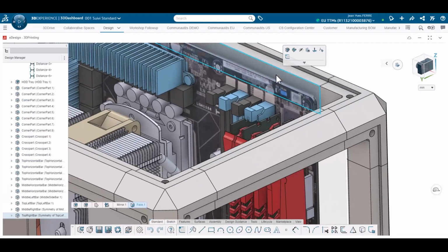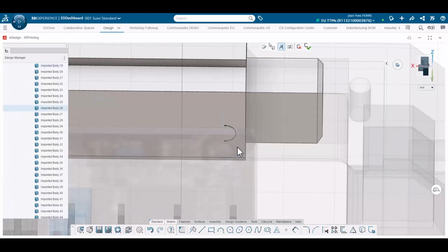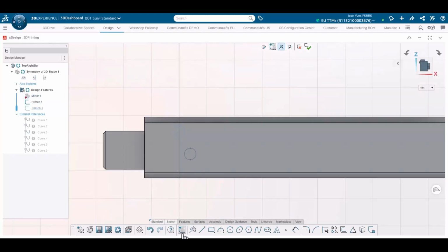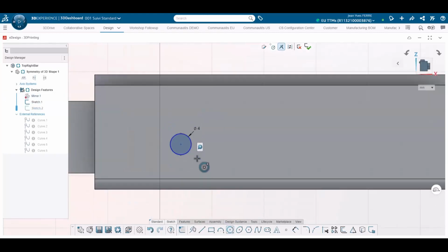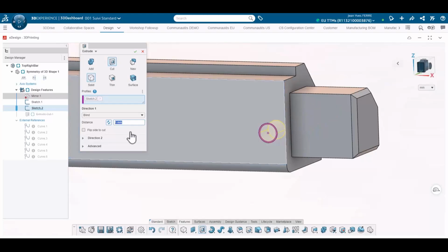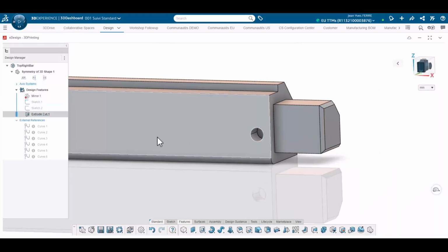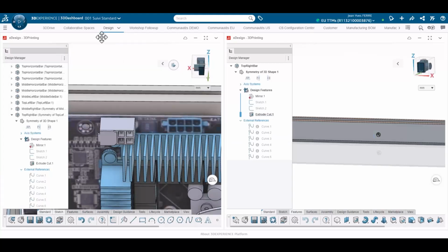I start with top bar, I project motherboard mounting holes, and let's be clear, this will be the easiest case. Holes are aligned with the bar. So I drill new holes aligned with mounting ones, and I will add some spacer columns to mount motherboard. I just create larger holes to accommodate threaded inserts, and design is done. Let's move to middle and bottom bars.